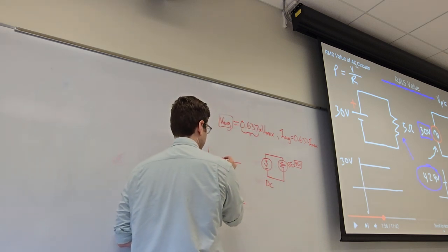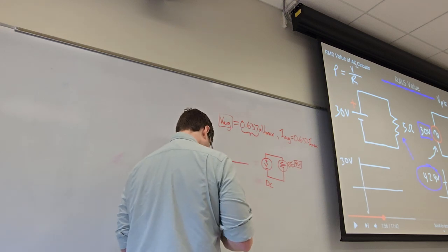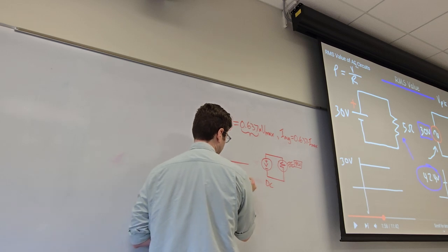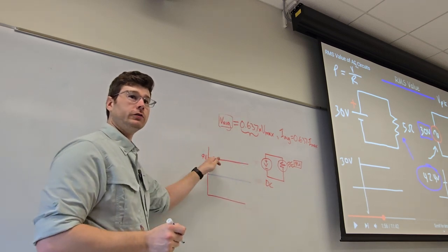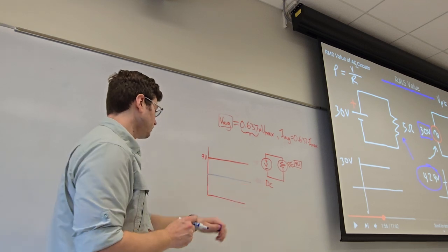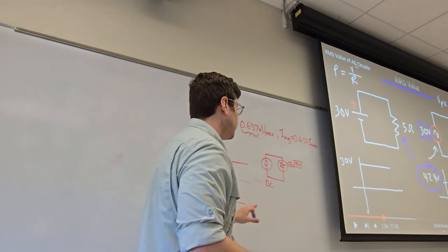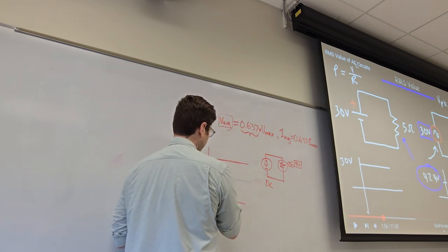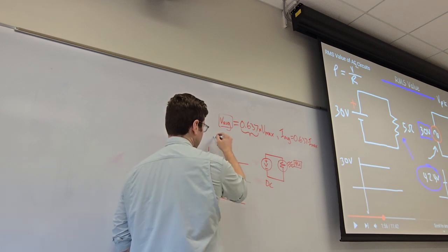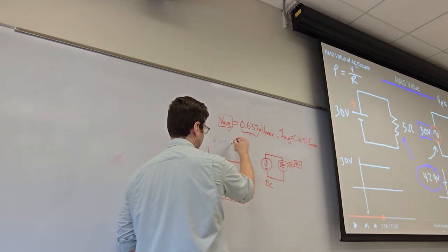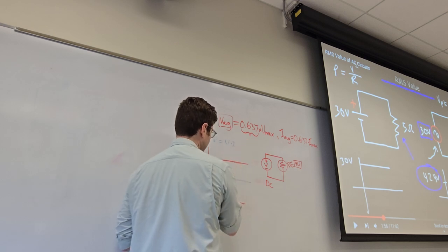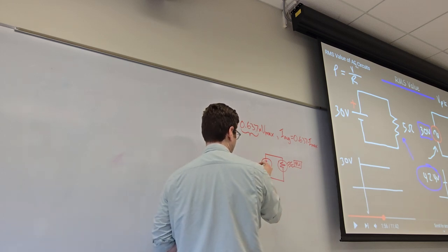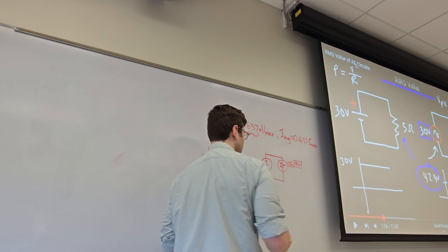So that looks like this. We have a stable voltage, and for that stable voltage, some amount of current will flow as well. This is our voltage, this is our current. It's not changing, it's the same no matter what. To get the power, this 9 watts that we calculated here, for every point on our chart, we look at what the current is and multiply by the voltage, where power equals volts times amps. So volts times amps, volts times amps, for each instant in time. Then we get our average power, which comes to 9 watts.